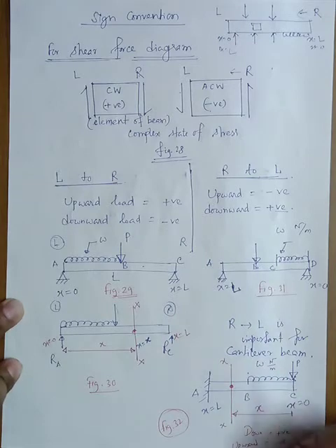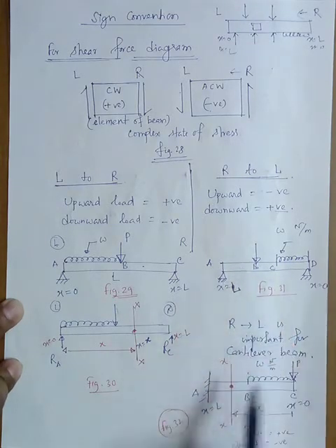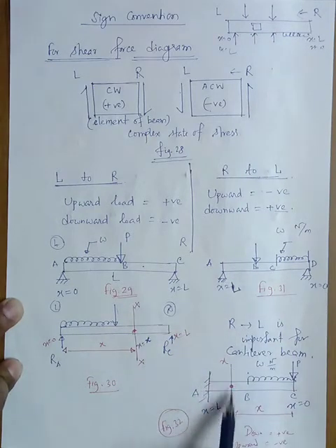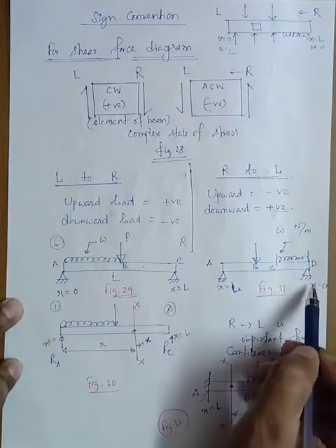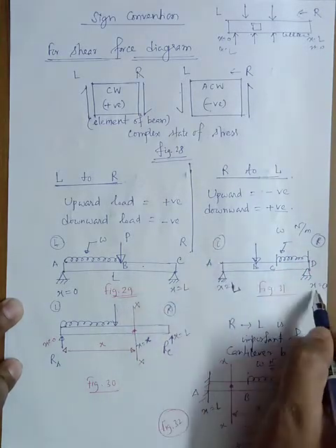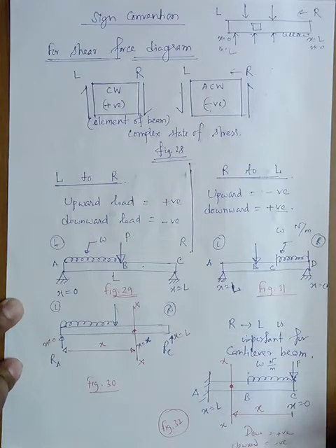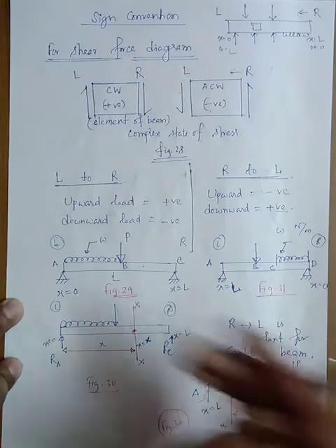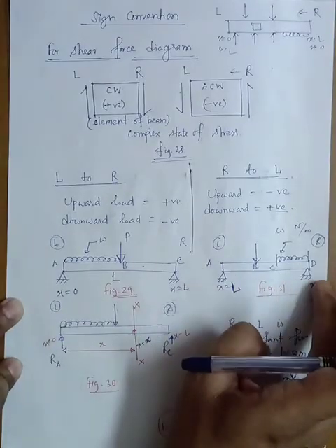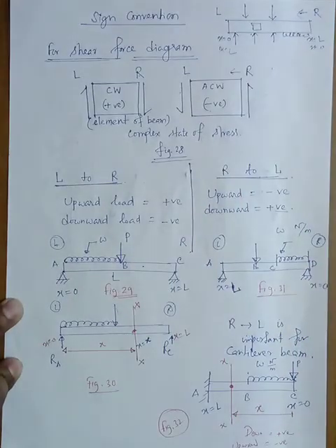Here, if you are asked to calculate the shear force at this point, you need to consider one section. Here I have taken the right hand as x equals 0. You can start from anywhere, from the left hand side or from the right hand side, no problem, but you have to obey the sign convention properly, that is the thing.